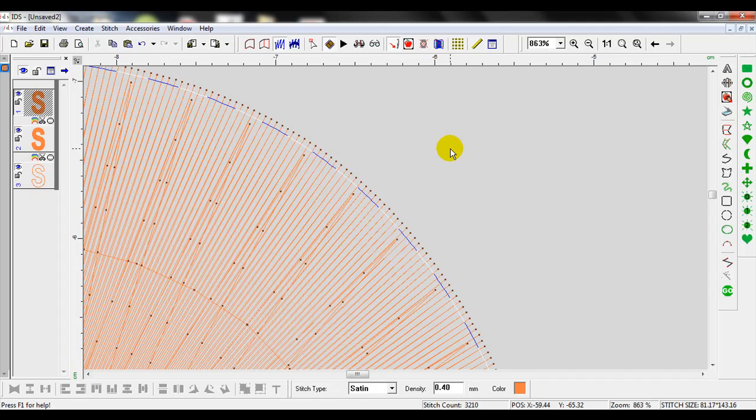So again, as that presser foot goes up and down on your material and the pantograph moves, the pantograph is actually guiding your material, and the needle is going up and down to create that pattern. And as the needle goes up and down, the pantograph moves. That presser foot's going to push against the fabric and pull against the fabric.